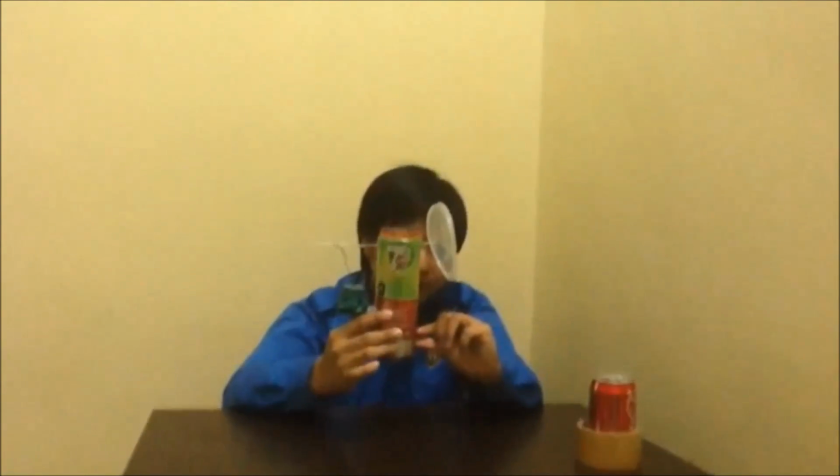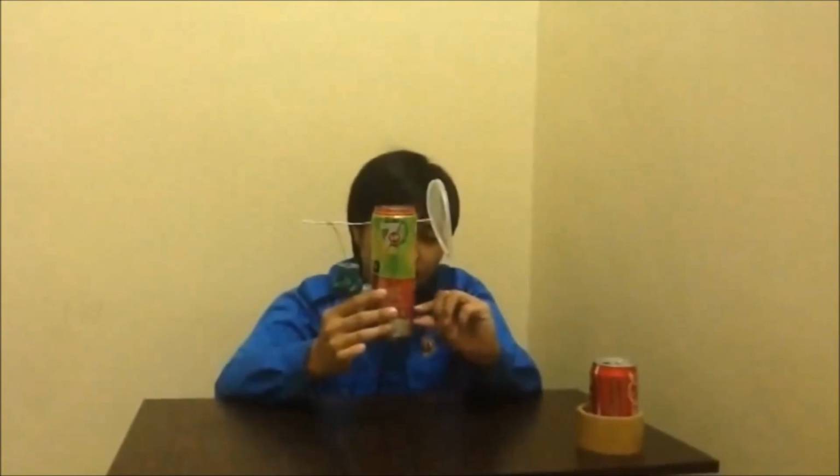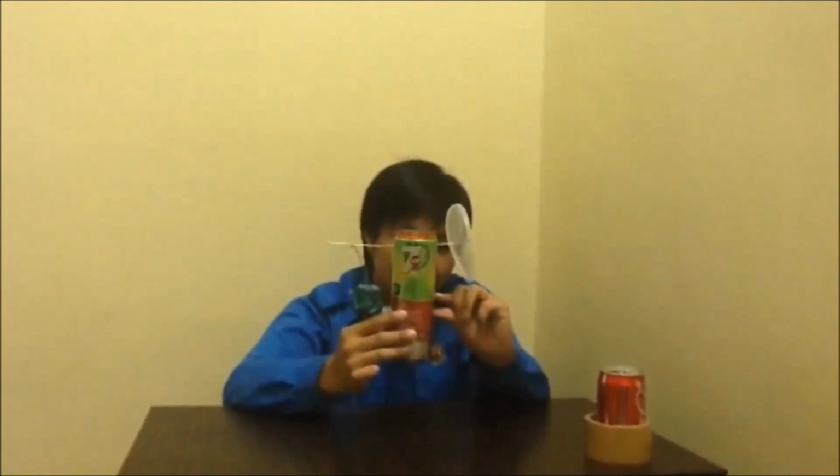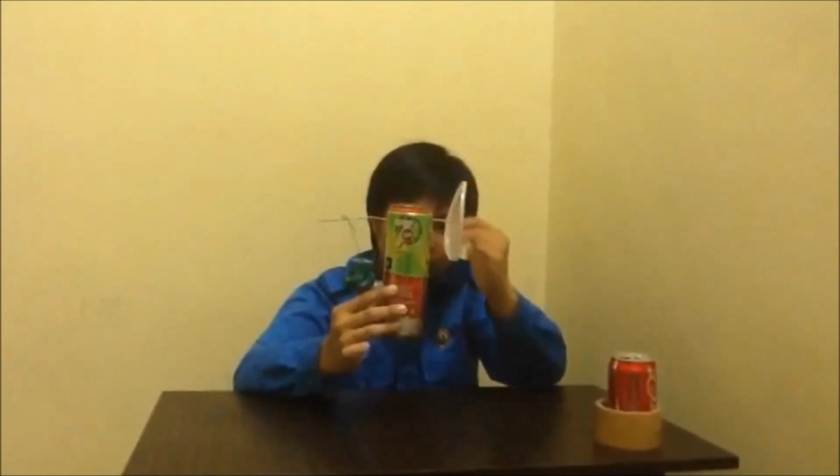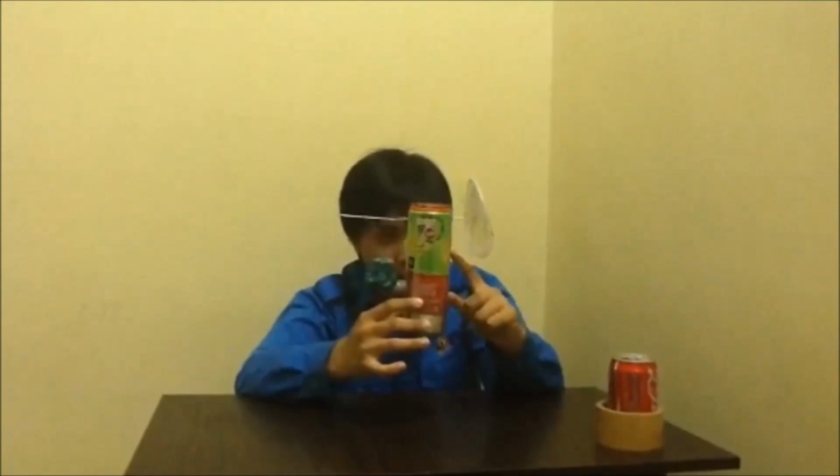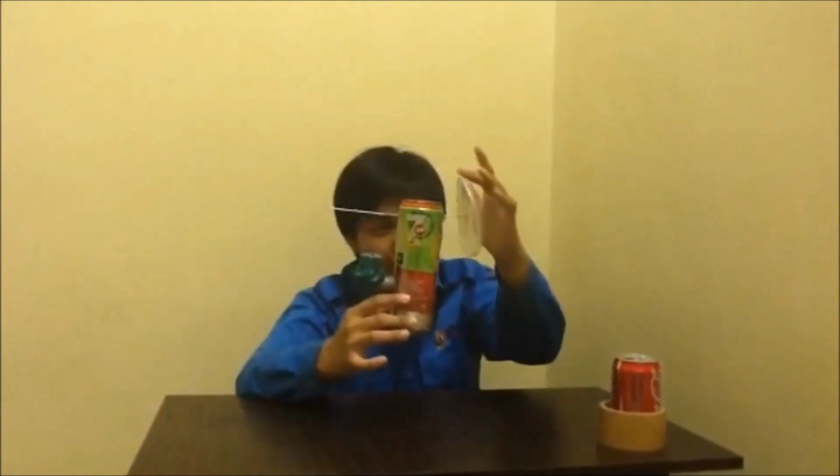So this balloon expands due to the heated air. Inside here there is a displacement piston. The displacement piston will rise up by the work input from the load and flow the heated air here and expand the balloon. As the displacement piston goes down by the gravity pull, the cool air here will be forced to flow to the working piston.